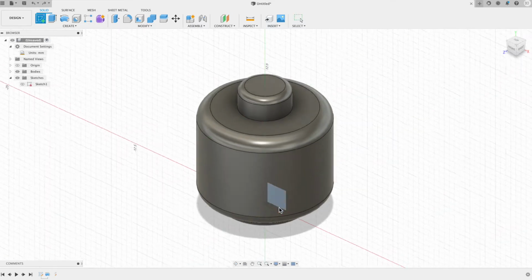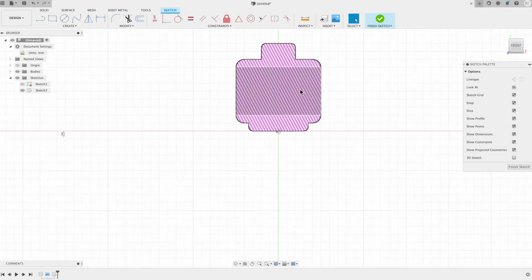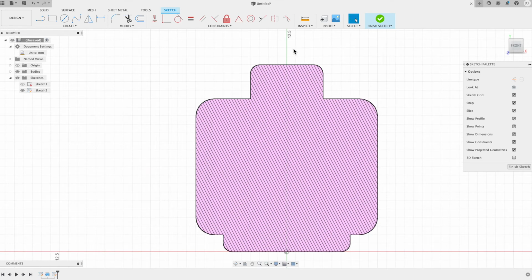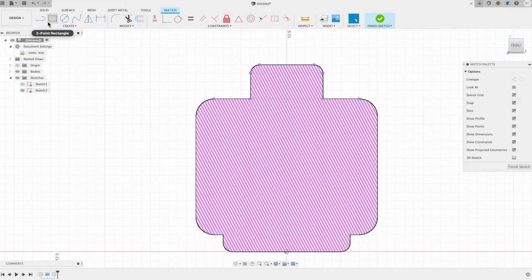So the next thing I do is I go over to the sketch icon and I click that, and I click the XY plane like we've always been doing, and that's the center plane. So that's what I want to do. I want to go into the center and I want to make some sketches and geometry, which is what you can see that I'm doing now.